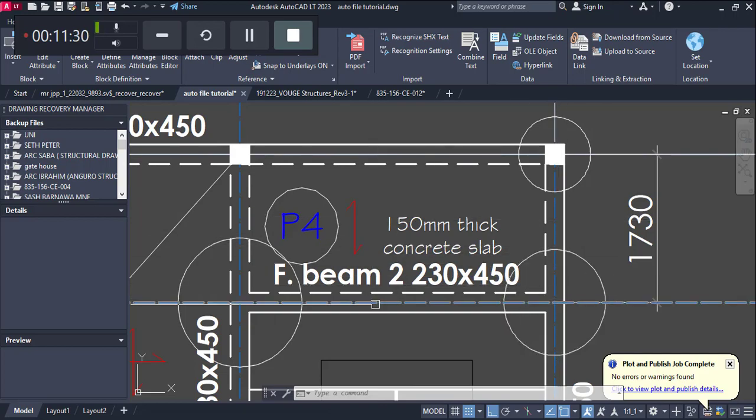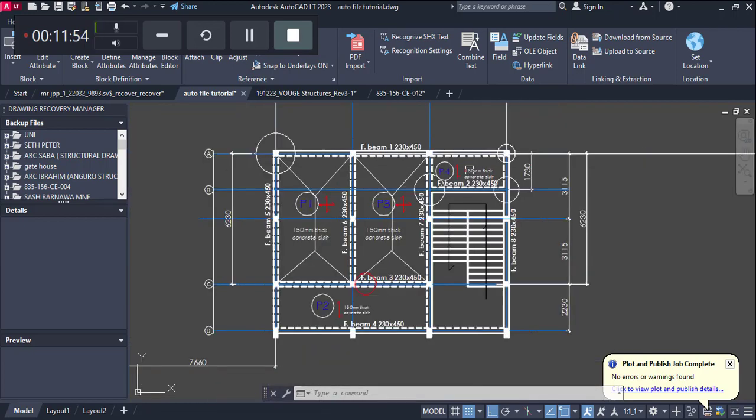That is also very similar when it comes to a cantilever. Most times, most of our cantilevers are one way, and in that case the load will come back to just that particular beam at this side. Most likely this one is literally not doing anything. So that's basically what a one-way slab means.